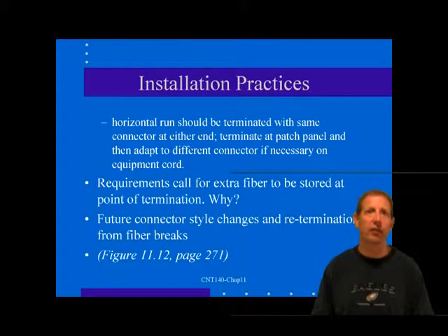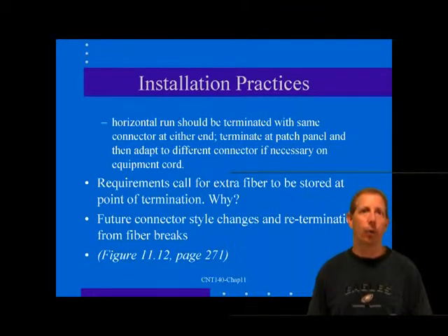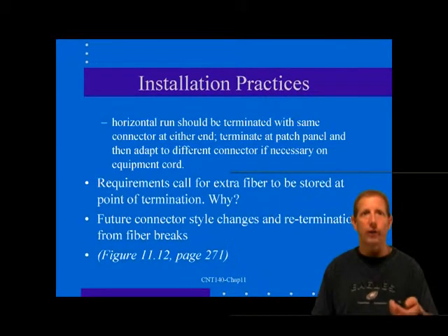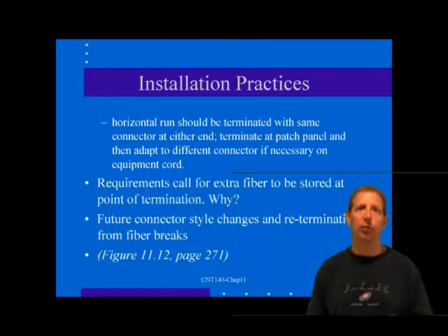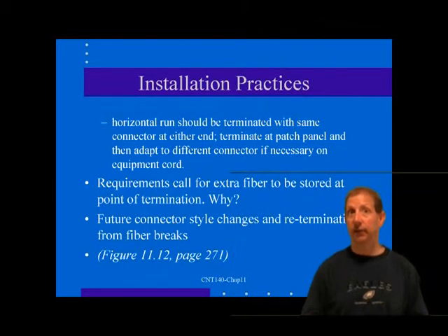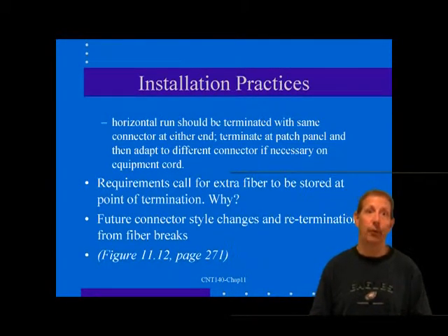Many of the connector designs are distinctly non-intuitive with respect to assembly. In order for the connector to operate according to its specifications, all the installation practices must be controlled right down to the millimeter. Connector designs are very different from one manufacturer to the other. Installers should be trained on the connector brand that they're installing, and the network managers should require training and certification of their installers and contractors.